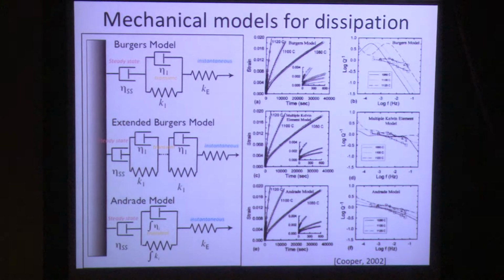But so this is, right, so Francis introduced, mostly he was talking in Q, dissipation factor, and it's the phase lag. The tangent of the phase lag gives you attenuation, which is inverse Q. So quality factor is Q, and then attenuation is inverse Q. And so it's just a measure of how dissipative the material is. And so this is a way of describing mathematically how real materials behave. Because that Maxwell model that had just an elastic element and just a viscous element doesn't describe the response of a lot of materials.